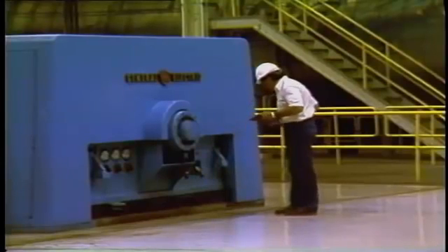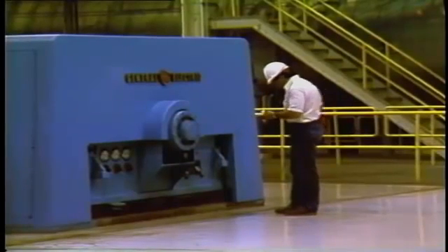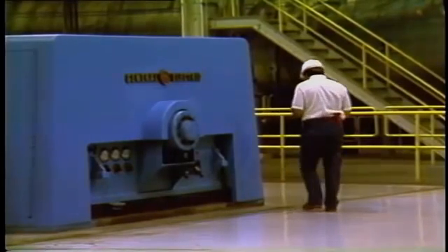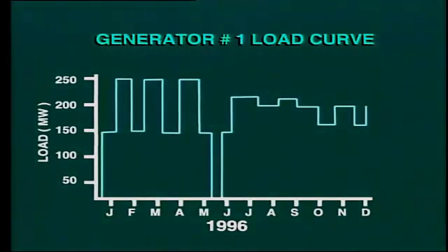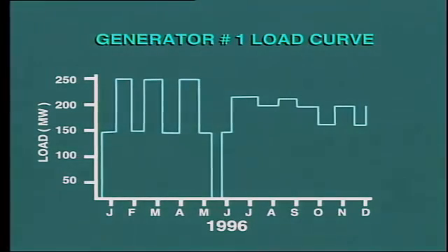It is vital that all protection devices be tested regularly to ensure that they will actually operate when required. In some plants, the turbine generator may remain on load for many months at a time. In this case, some form of simulated test may be carried out. For example, partial operation of the overspeed trip mechanism is actuated, but actual tripping of the turbine is blocked.